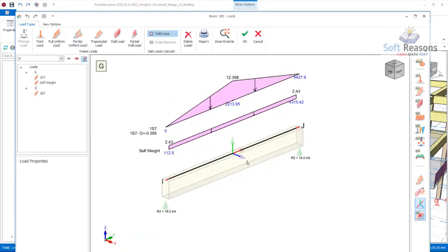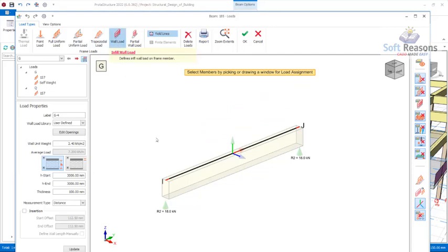So for you to now add the wall load, what you just have to do is click on this wall load. Yeah. So once you click on the wall load, you can have the details, the load properties. Okay. So in this load properties, you see wall unit weight, which I just explained. Originally it is 2.4, okay, for a 9 inches block. All right, it is 2.4 kilonewton per square meter based on the codes and the laboratory test.